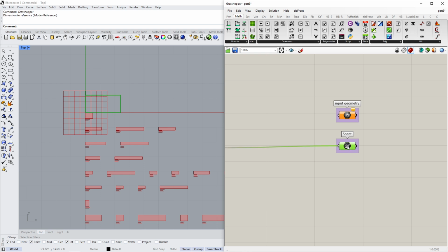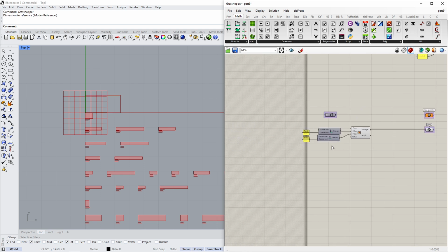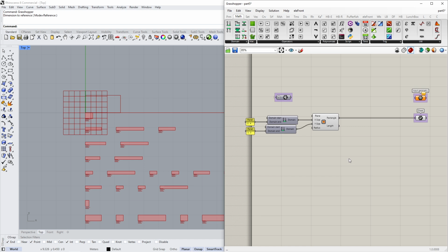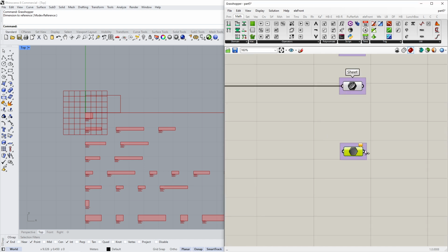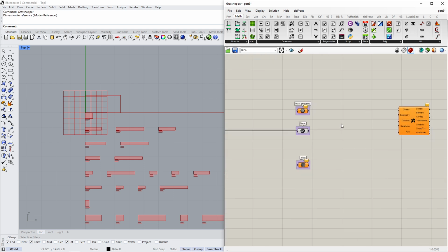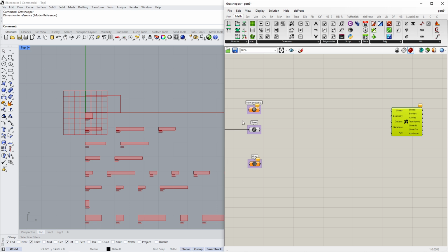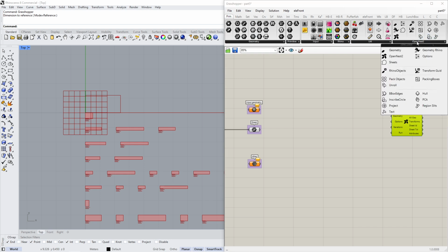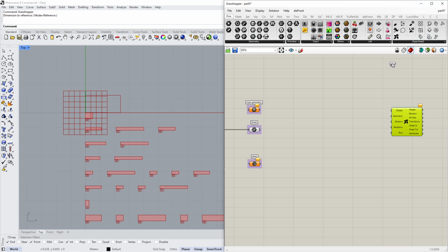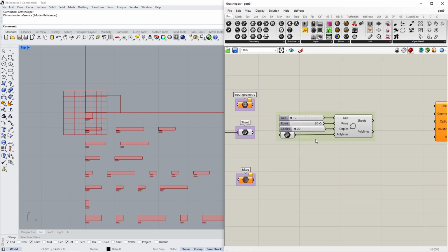And then the last thing I want to also put is the attribute, which is going to be our ID tag. So I'm just going to put a data component, call this ID tag. Okay, so before we can insert this rectangle directly in sheets, you have to convert it to a sheet, a special geometry type that OpenNest uses. And that is this component here, sheets. And if you insert it, it will come already with some inputs. That's very nice. And for now, let's keep these at its default.